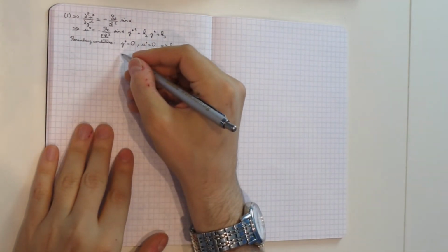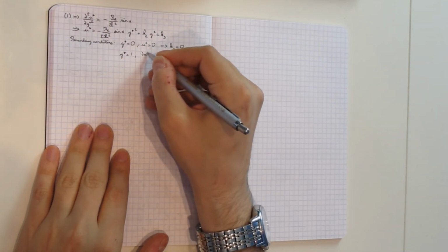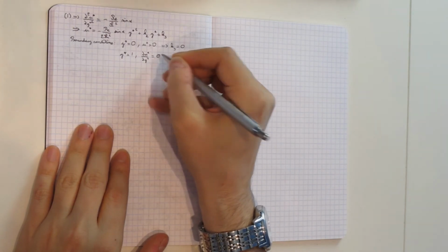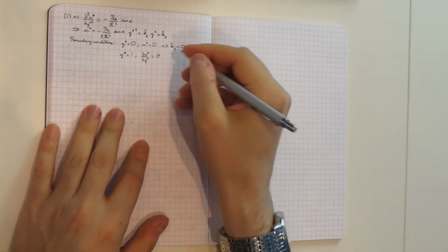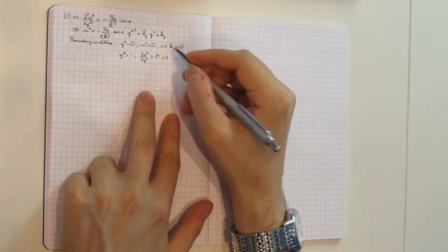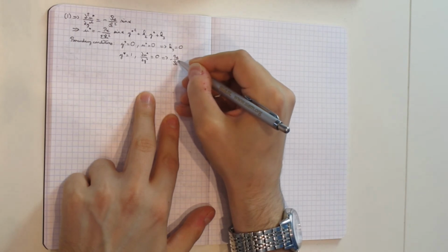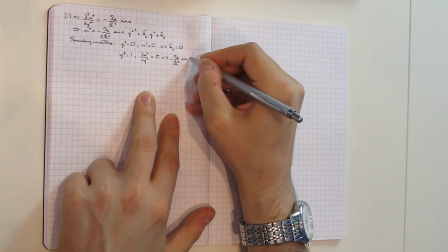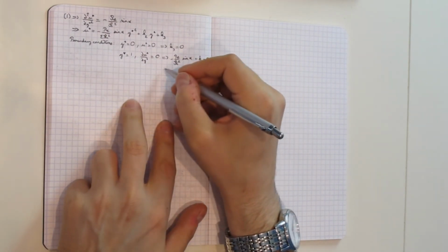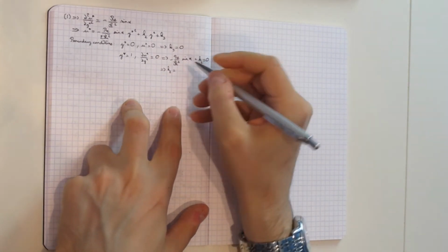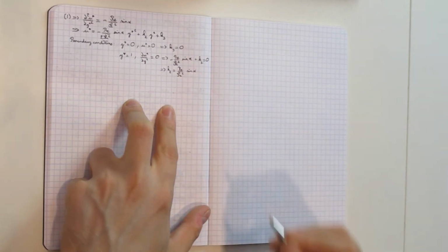And the other boundary condition, as we saw, is that at y star equals 1, du star by dy star equals 0. That says that there is no friction at this free surface. That essentially gives us here that minus the Reynolds number over the Froude number squared times sine alpha plus K2 equals 0. In other words, K2 equals the Reynolds number over the Froude number squared times sine alpha.